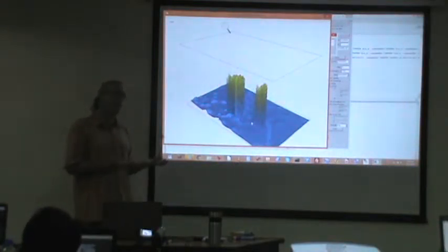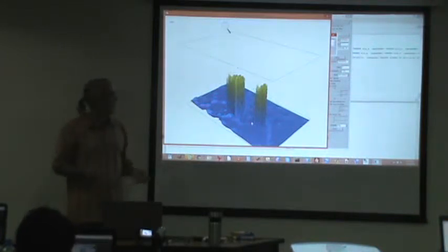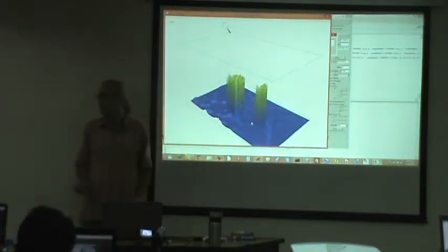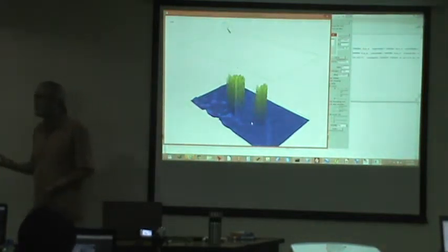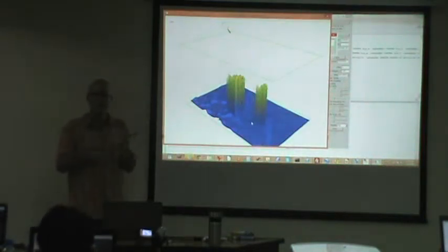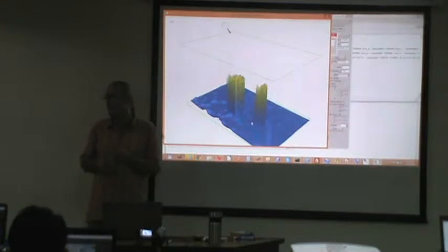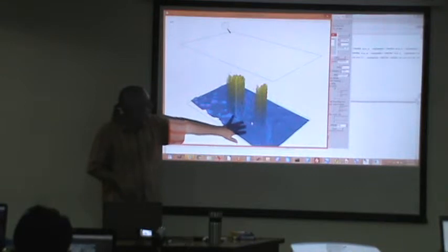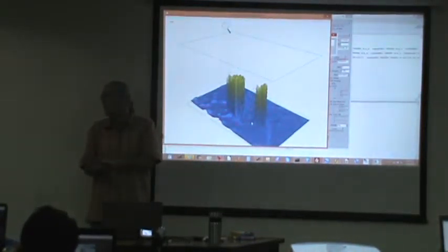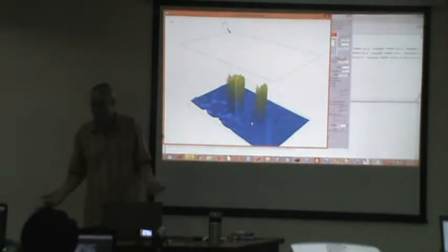They are not so detailed, they don't produce good flood models, but they can tell if it's a cloud or not, because they're going to be at least that good. So there's SRTM and ASTER data that exists that we can use to tell us, well, we know plus minus 20, 30 meters where the surface is. And so if it's 100 meters above that surface, it's probably not the surface.